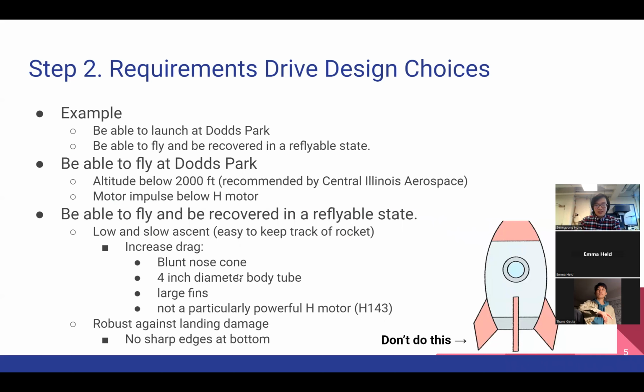There are two types of motors: reloadable motors and single-use motors. Single-use motors, you just plug into the rocket, and after it's burned out, you throw away the whole thing. With the reloadable types, you have a casing, and the part that goes on screws into the casing itself, and that tends to be a bit cheaper in the long run since the casing is reusable. It's just the inner parts that you swap in and out.